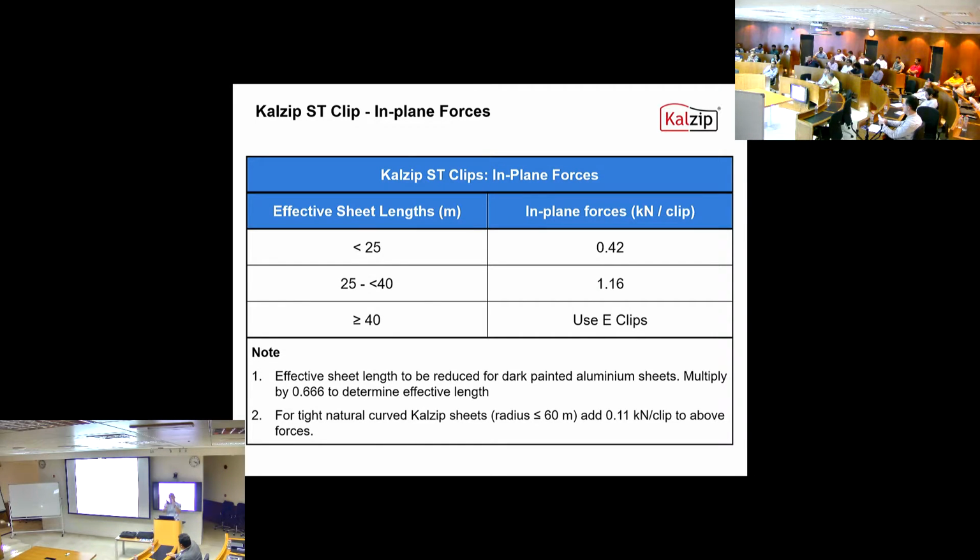But what happens, the sheets may rotate a little bit and then pop back, because you hear when you're on site, you hear the clicking noise. That's it clicking over the head of the clip. So is what you're saying for 300 wire? Yeah, that's right. We look at the worst case. We're assuming these figures are assuming the worst case: clips slightly installed out of tolerance, worst thickness 1.2. So these have got a bit of safety factor in there.